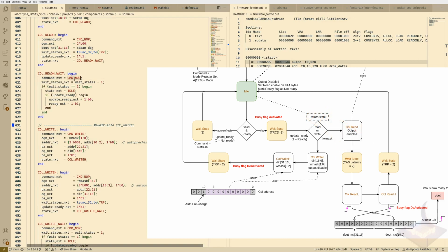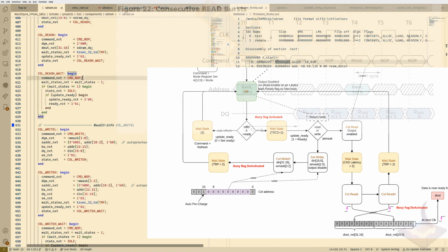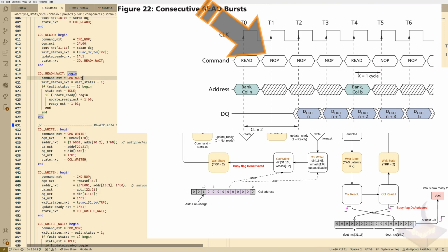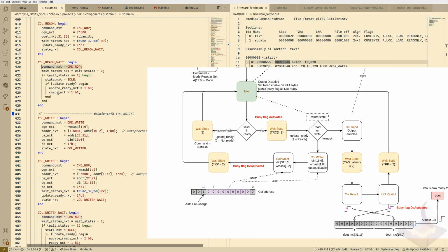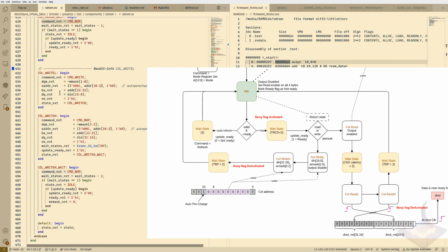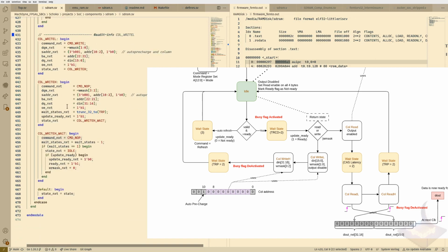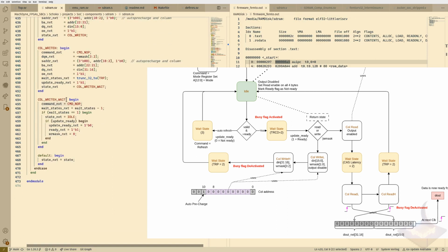You saw that in the timing diagram on the specs itself. We're using the no op. You have to set this no op. If you don't, the device will see something other than no op and immediately abruptly finish any command, or even abort the command and try to execute the new one. So you definitely need to make sure that you have no ops while the command's processing itself. And the same thing for the write. We're going to issue a row, and then we're going to issue addresses that are part of the column. And once you're done, you wait for that. So that's the entire thing.